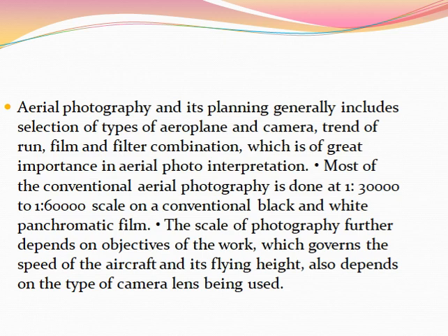Low flying speed and height are among the most important aspects in obtaining sufficiently large scale photographs with sharp images of objects. There should be complete stereoscopic coverage of the terrain, that is, all features of the terrain should occur on at least 2 photographs for stereoscopic viewing.